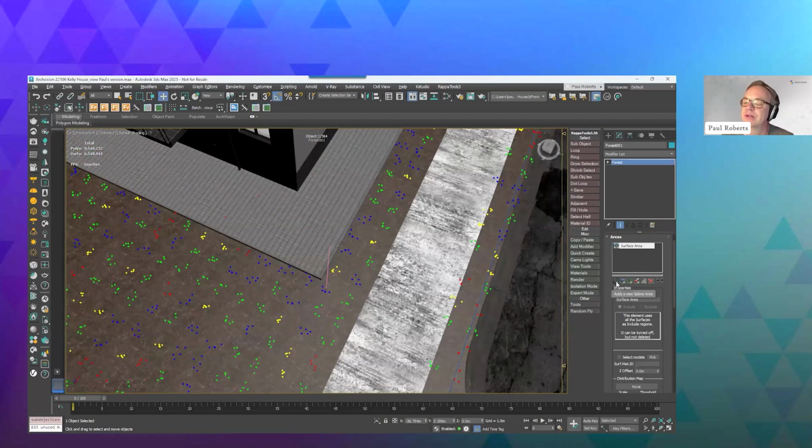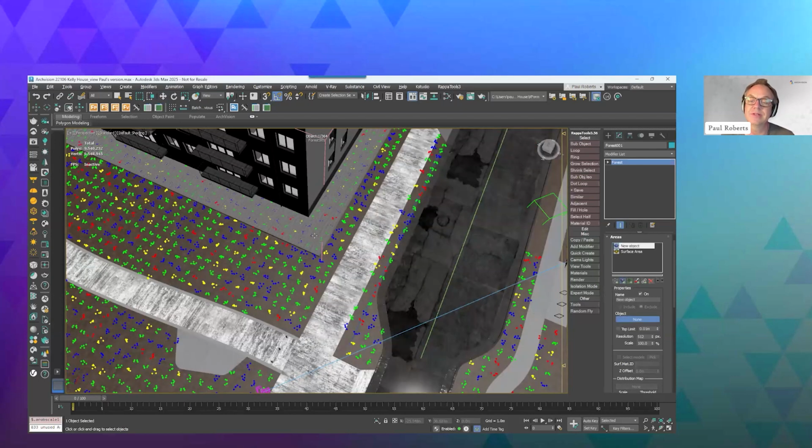You can see I've got 5 types. I've got a spline area, an object area, a forest area, a paint area, and then a link area, which we won't worry about today. This is an object I'm trying to exclude from, so I'm going to click on object and just zoom out so you can see it there, and click on that. And you can see it removed it from there.